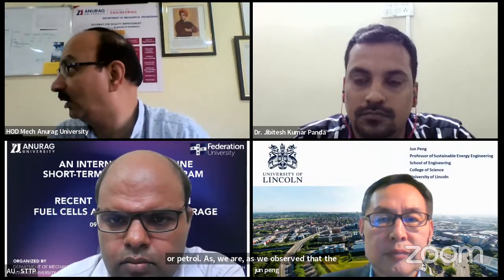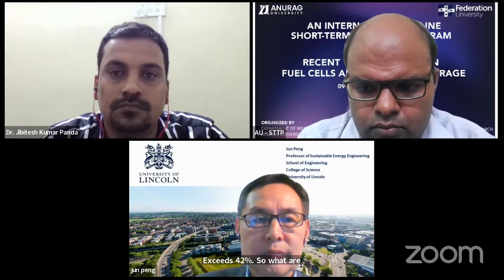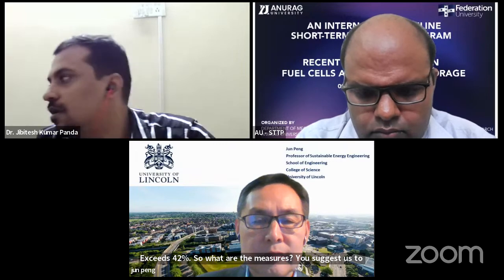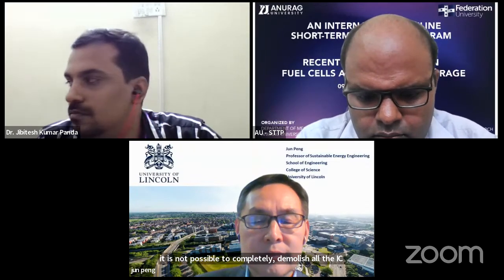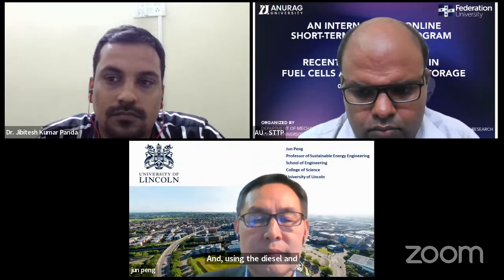Nabia madam, are you there? Yes, sir. Can you hear me? Yeah, please. Sir, I have a small doubt. Today in the current scenario, to replace the engines all at once is difficult, because we have main issues like waste management and also the economy. For us, there is only one possibility: to continue with the IC engines along with hydrogen, along with the diesel or petrol. We observed that detonation occurs when the hydrogen content of the total fuel exceeds 42%. So what measures do you suggest to overcome this situation and increase the hydrogen energy content in the vehicle, sir? It is not possible to completely demolish all the IC engines using diesel and petrol and move to hydrogen fuel cells.